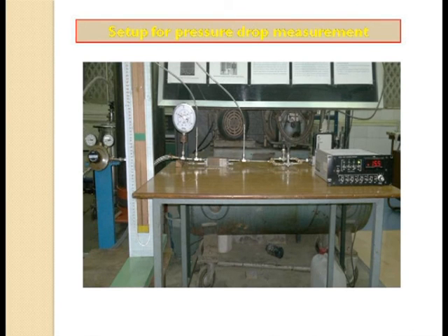Okay. Then this is pressure drop measurement. Pressure drop measurement is another issue. Every heat exchanger should be tested for its pressure drop and also its thermal performance. Pressure drop is the hydraulic performance, and if you have higher pressure drop, then that heat exchanger is of no use, because you have to pay in the compressor to raise the pressure and then pass the fluid through the passages. So this pressure drop measurement, we have done separately outside.